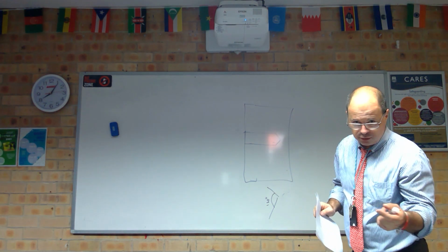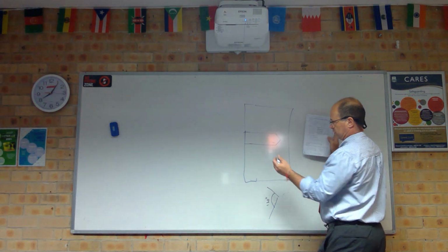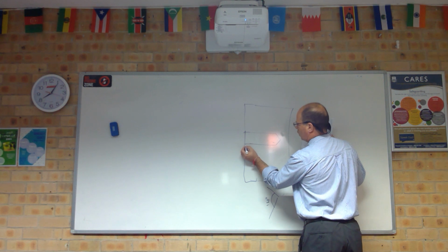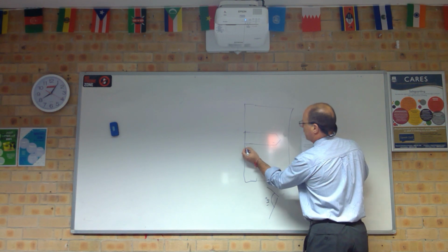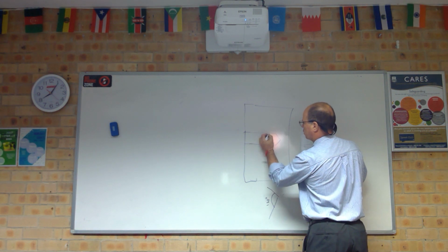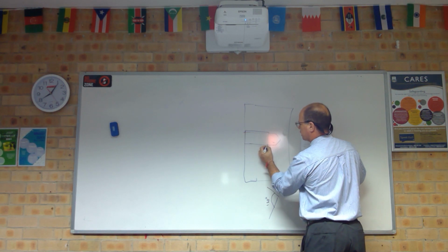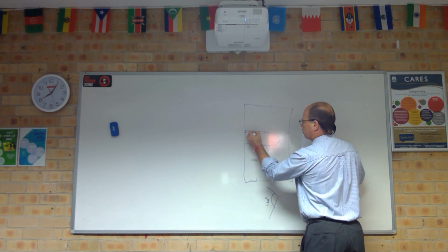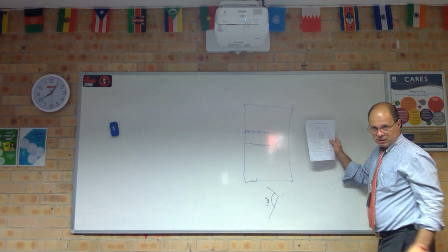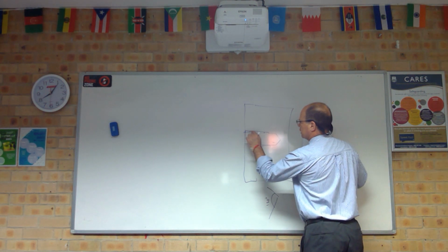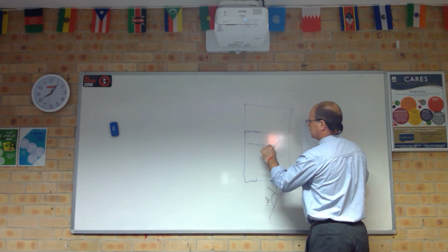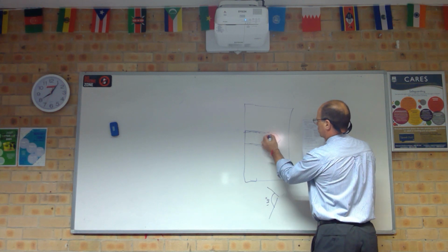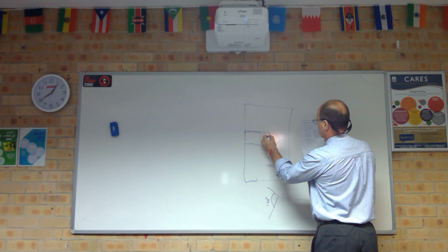And then after we drill the hole, and you've got a video on drilling and tapping, so you'll be able to watch that video. What happens then is we tap the hole to a certain depth. So we'll be cutting thread all the way along here. And once we cut our thread in, we draw a line across, because that is where the thread is ending.